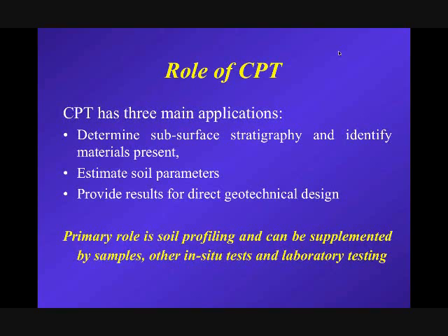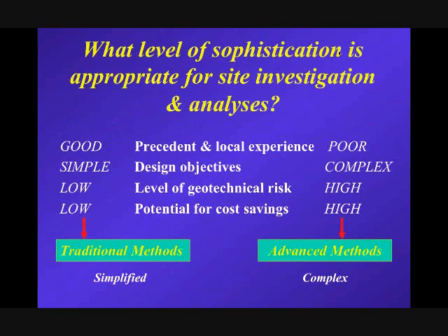When the device was first developed in Holland, the Dutch used it for pile design, and so pile design is certainly one of the most mature direct geotechnical design methods using the CPT. But others have been added. You can estimate the bearing capacity of shallow foundations, and you can estimate liquefaction resistance directly from CPT results.